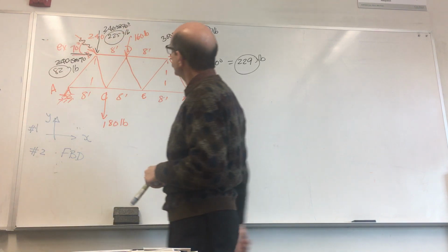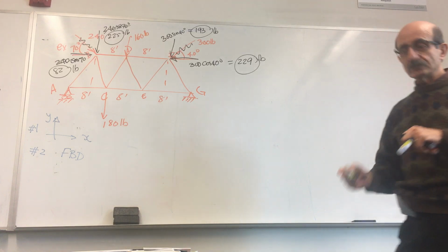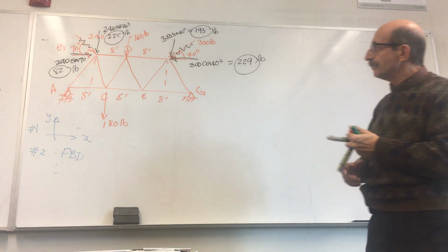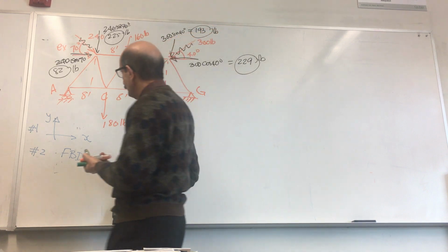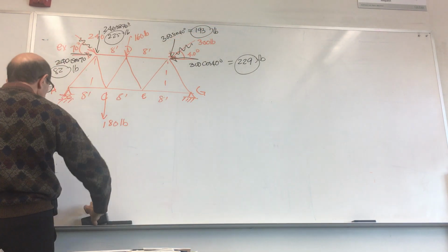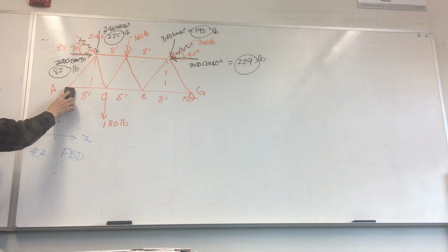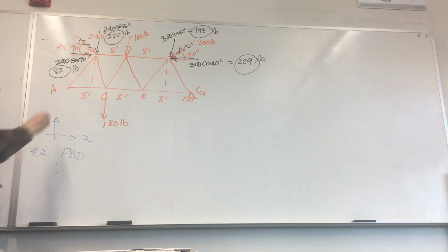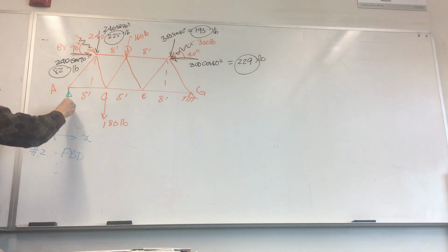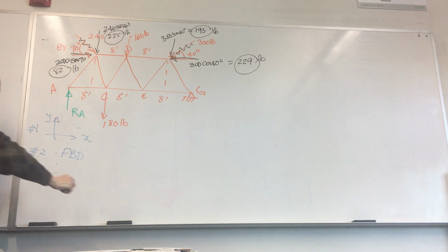Now we have better looking forces. So, free body diagram, right? We have those external forces. Remove this support, which represents how many unknowns? Direction of motion is this way, so you have only one unknown perpendicular to the direction of motion, at A. How about this one?